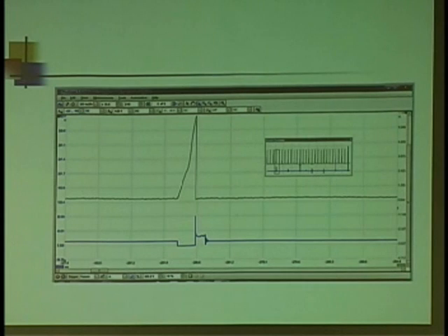On that pattern, you're going to see it's the same as the secondary, except in the firing line. You won't see the same level there. But the burn line, the spark line, the one with all the information in it, that's a mirror image of the secondary.